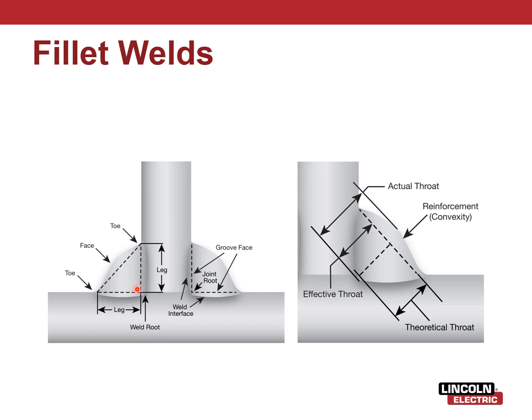And with T-joints with fillet welds, 99% of the time you're wanting equal leg lengths. Very rarely does something call for unequal leg length. So keep that in mind when you're welding. That's one of the things I get pickiest with about my students, making sure we have equal leg lengths, because that keeps that structural shape, the symmetry, and that's going to be the best way to weld. That gives it the most structural rigidity.